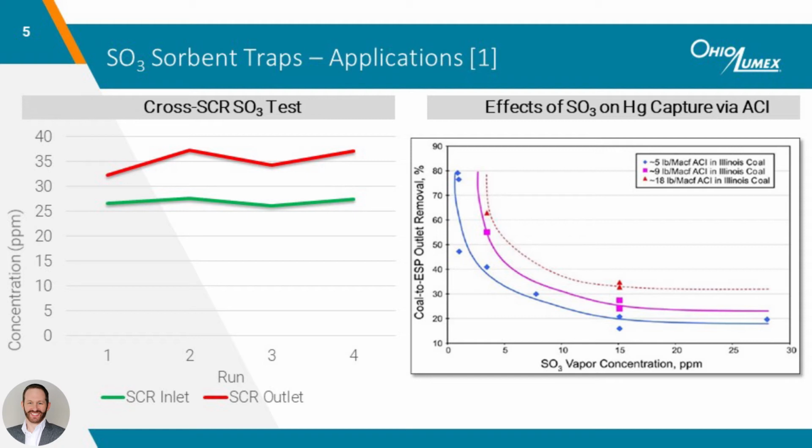Many coal-fired units around the country have been required to run at very low load for extended periods of time, which exacerbates ABS formation due to the reduced operating temperature. The ABS formation temperature is a function of several variables, including ammonia and SO3 concentrations. Essentially, if SO3 concentrations can be reduced, it is possible to run a coal-fired unit at a lower minimum operating temperature without creating problems for the SCR and air preheater.